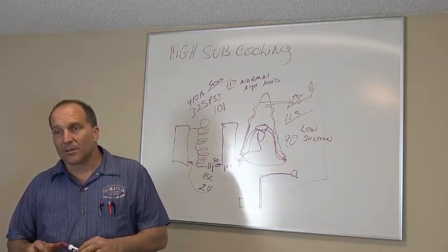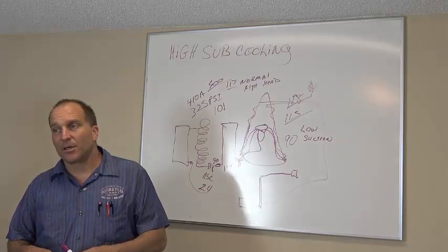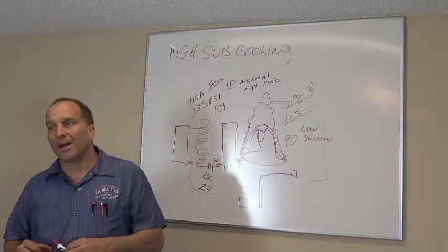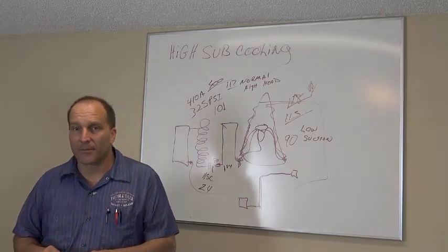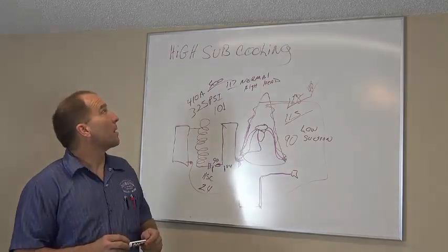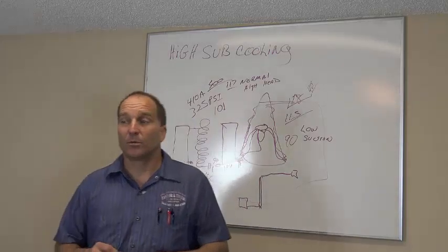When you get to a system, check your head pressure, check your suction pressure, check your superheat, check your subcooling. Now you know where the system stands. All right. Let's go to low subcooling, and we'll go from there.